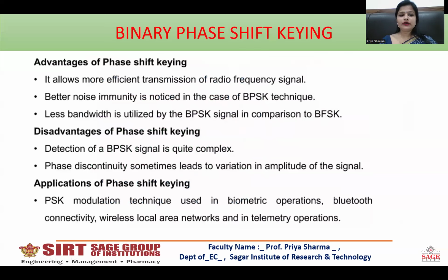Advantages of PSK include that it allows more efficient transmission of radio frequency signals. Better noise immunity is noticed in the BPSK technique. Less bandwidth is utilized by the BPSK signal in comparison to BFSK. Disadvantages include that detection of a BPSK signal is quite complex. Phase discontinuity sometimes leads to variations in the amplitude of the signal.